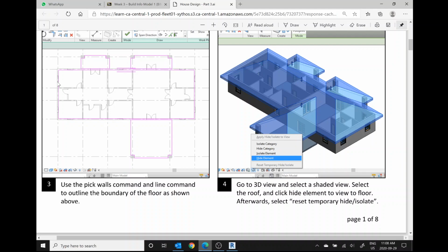So basically what it's saying is it wants us to do a floor along the interior perimeter of the wall, but then we have these 3 types of outdoor spaces that are going to be paved or have a concrete floor. So patio type of spaces or driveway type of spaces, and so these are all going to be separate floor slabs.